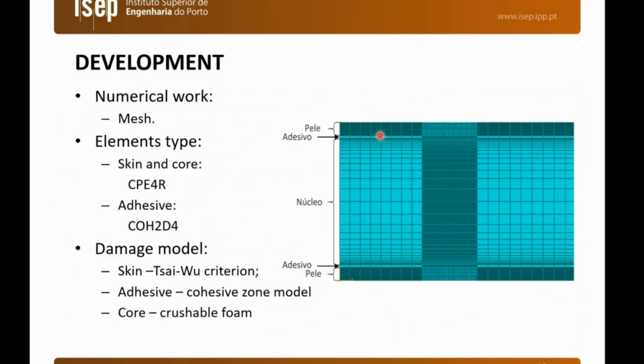In terms of damage, the HGE criterion was considered for the cohesive zone model, with a triangular law considered for the adhesive, and the crushable foam damage model was considered for the core of PMI foam.